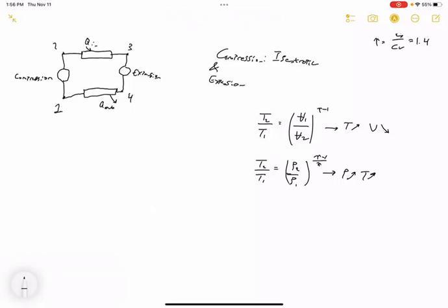And the last one we're going to do, the last isentropic relation, is this. P, this is supposed to be pressure, not rho. P2 over P1 equals specific volume 1 over specific volume 2 to the power of gamma. Again, to us, this makes sense from the ideal gas law, right? So as specific volume goes up, pressure goes down. In other words, as the density decreases, so too does the pressure.